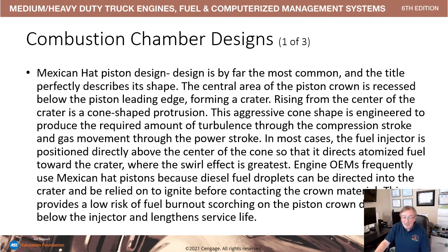Okay, your Mexican hat, we have those. We're going to show you those in class. The injector tip is located right over the top of the hat. OEMs frequently use Mexican hat pistons because diesel engine fuel droplets can be directed into the crater, and it creates some swirl, and it lowers the risk of burnout, scorching of the piston crown.